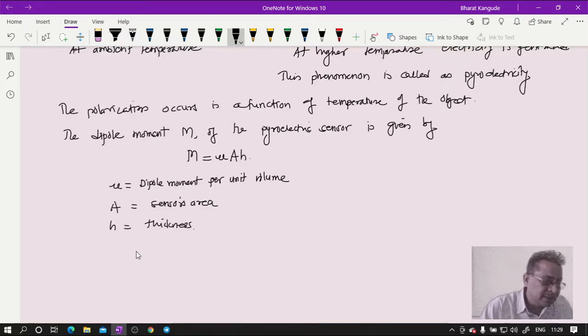But the devices which use this principle of physics, that pyroelectricity is generated because of radiation, and radiation is a characteristic of the temperature, are nowadays very popular for measurement of temperature. And that is an advantage I have talked about several times, that these devices do not need to touch the object of which we are supposed to take the temperature.